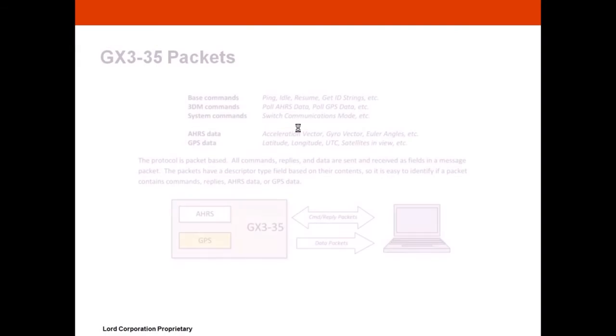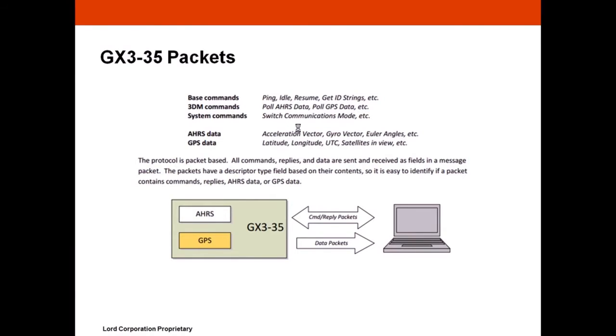Anytime you get data that has that full descriptor, you know that it's exactly what I just described. No variance. You can't switch the order of the axis. You can't change to a different type of floating point. You cannot use a different scale. You cannot use 1 or 2 floating point values instead of 3. You have to do exactly this, and you can guarantee that that data is going to be valid. It turns out to be a very, very powerful concept when you're parsing sophisticated data, especially from an AHRS or